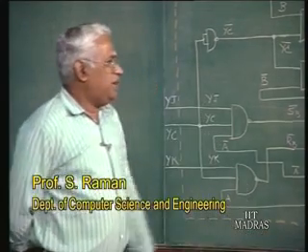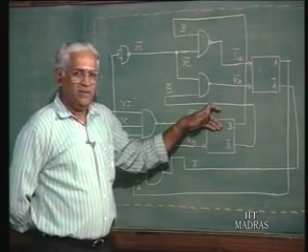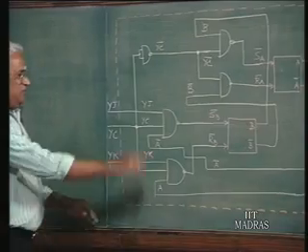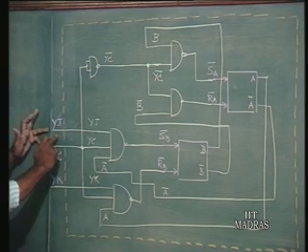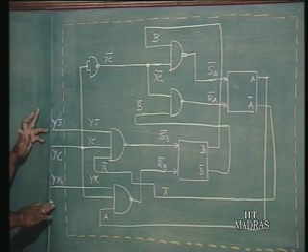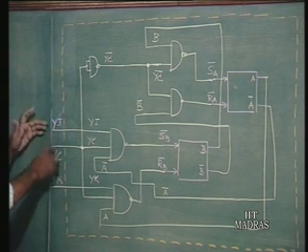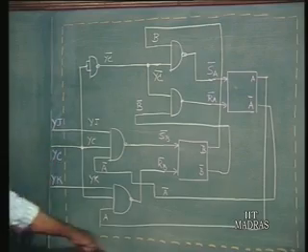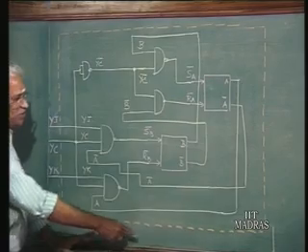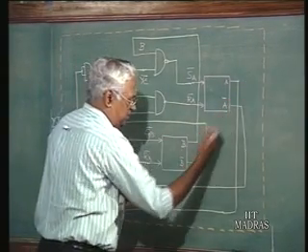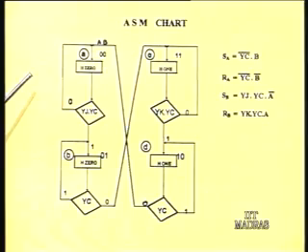The output will also incidentally be derived making use of the 2 state variables A and B, right. We will do that. How is it? We have to in fact refer to the ASM chart. Now, we just say YJ, YK, YC are the 3 inputs I said, and then the outputs are H1 and H0. Okay. So, you can see that these are the 3 inputs from the external world, and what we have internally is our digital system or machine or component, whatever you call, and the output will have to be generated, which again will be a function of the state, which means A and B. Let us go to the ASM chart.